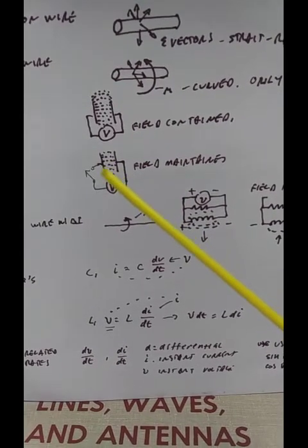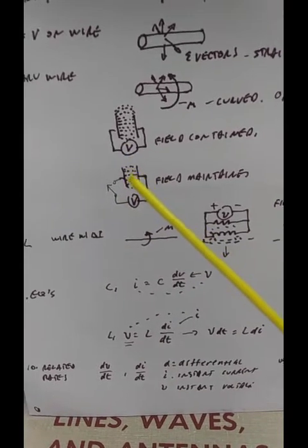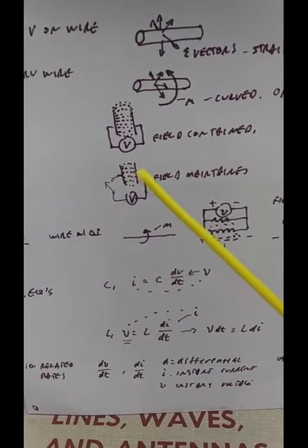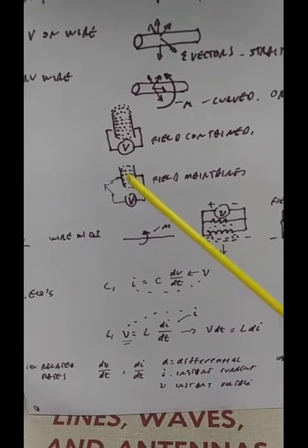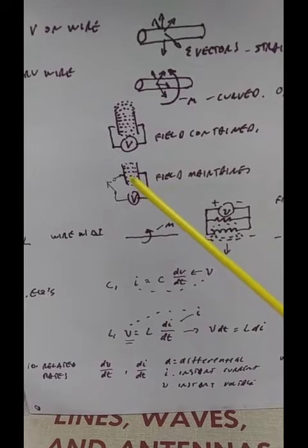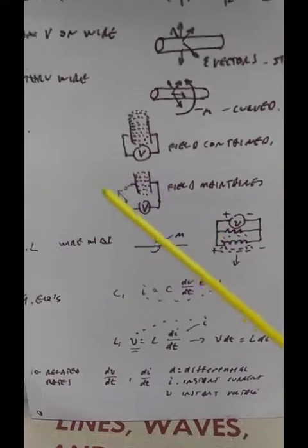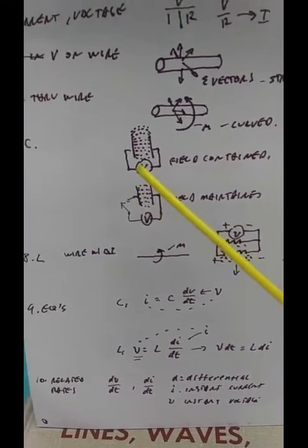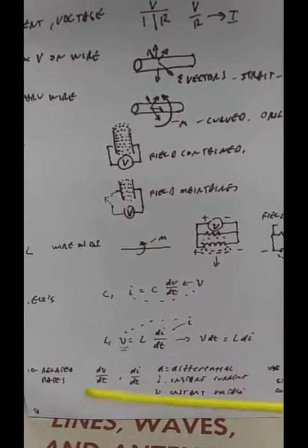It did not store current. Current is the flow of electrons. When a capacitor is in steady state, there is no current flow, period. Capacitors don't store electrons. They don't store electricity. Current does not go through a capacitor. Capacitor dielectrics, ceramics, plastics are on the order of times 10 to the 14th to 20th power ohms. Extreme resistance. Why? We don't want leakage current, because leakage current results in low Q and eventually breaks down the dielectric and destroys the capacitor.